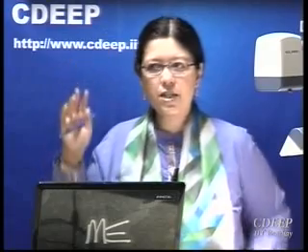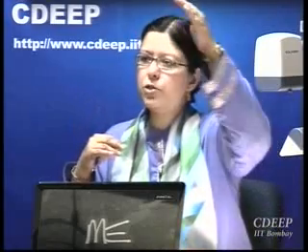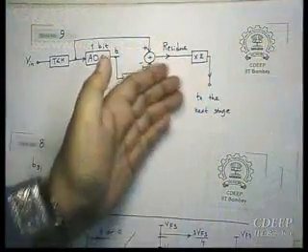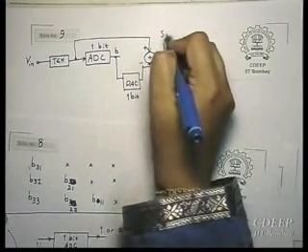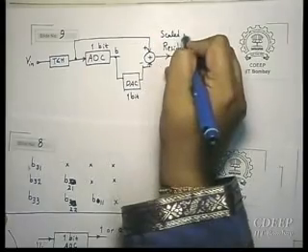Therefore, one of the main drawbacks of pipeline ADC is that if you don't take care of these inaccuracies, the middle stages may get saturated. Because if your error goes more than some value, you actually may reach the full scale level, because this is an analog level, right? This analog level is the residue multiplied, a scaled up version of the residue.